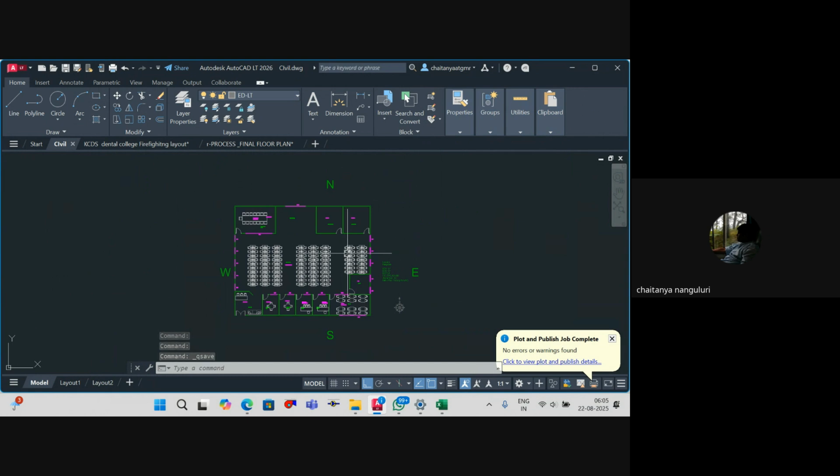Okay. So for this, we'll be working on heat calculations. Rule number one: you'll always calculate heat load for summer conditions. Because if you're able to satisfy a client in summer, don't you think during other seasons people will be happy with the air conditioning solution? So for that reason, we always design for the worst day situation. I'll explain the probability of worst situations later on. Let's not complicate at this point. So we will take summer condition, number one.